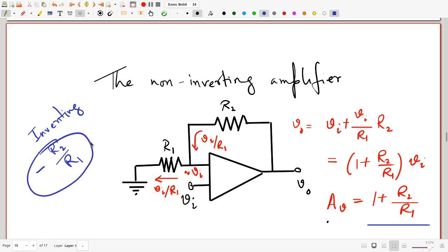Another point, and this one is a demerit for the inverting amplifier, involves the input impedance to the amplifier. Not the input impedance to the op-amp, but to the amplifier. Of course, the input impedance of the amplifier is simply how much the input voltage is divided by how much current is drawn by the amplifier. Notice that in this example, the current drawn by the amplifier is almost 0, because this input is directly feeding into the op-amp itself, and the huge gain of the op-amp.